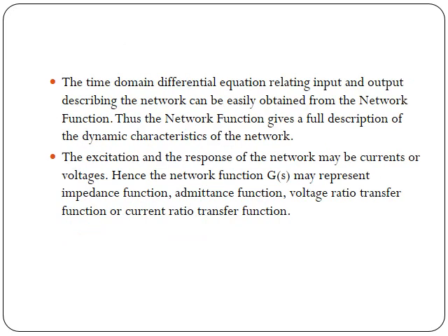Now the next property is that the time domain differential equations of the input-output can be derived from this network function easily, and thus we can say that the network function gives a full description of the dynamic characteristics of the network. That is, if the network function is given, then we can totally define the characteristics of that particular network.